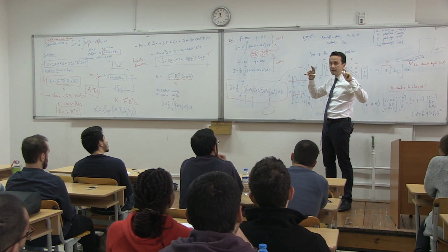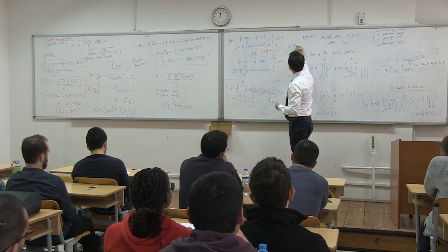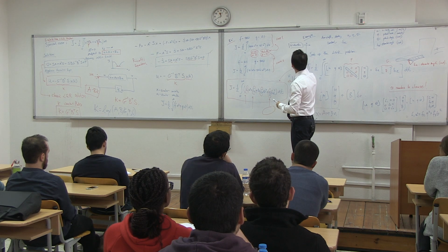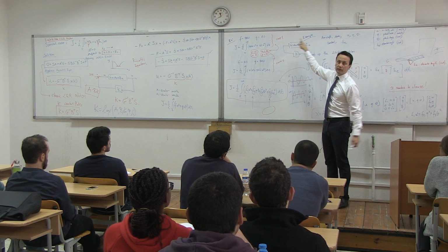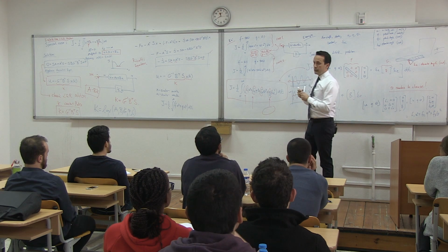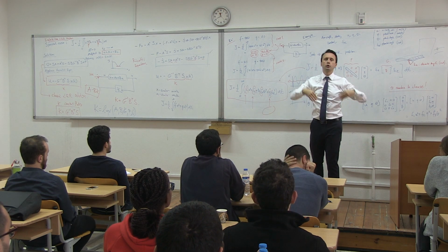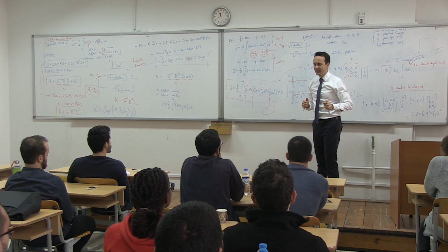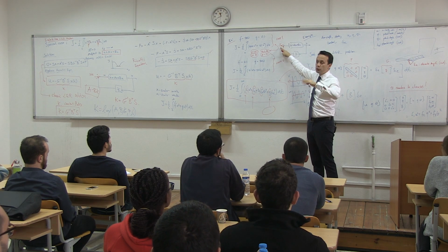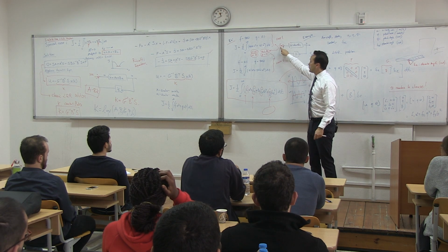Okay? And this is just stabilization. This is just stabilization because we are still doing this: X dot is equal to AX plus BU, with X times K. Boom. You're just stabilizing still. There's no control over here. If you add this guy, this loop will try to stabilize the system, and this guy is trying to give the control to overcome that stabilization. All right? So they will be fighting. This will try to bring it back to equilibrium. This one is trying to remove it from equilibrium. So if you find the right balance, you will have a stable aircraft where you can still control it.